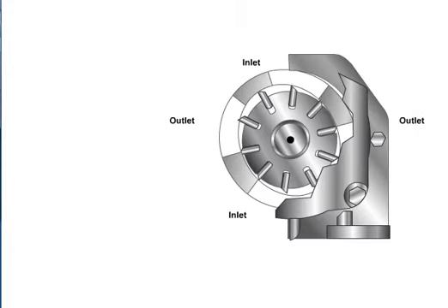It is important before viewing this animation to understand the unbalanced vane pump. If you need to review it, go back and click on Unbalanced Vane Pumps. In the unbalanced vane pump, which has been previously illustrated, one half of the pumping mechanism is at less than atmospheric pressure. The other half is subjected to full system pressure.